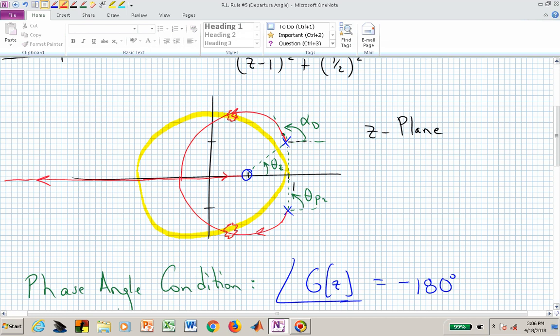Now we want to know, how much do we crank up the gain k to get to that location? We could find that with a little trigonometry. This distance is really a radial distance because we have 2 poles and a zero, and if we envision those 2 poles rotating to be real, they would stay that same radial distance away.